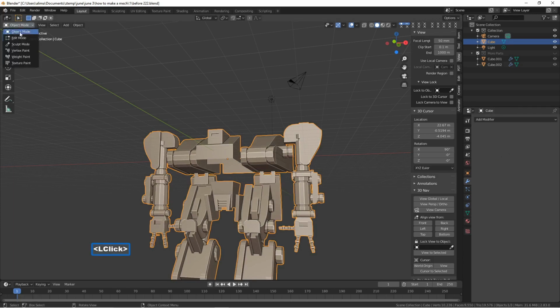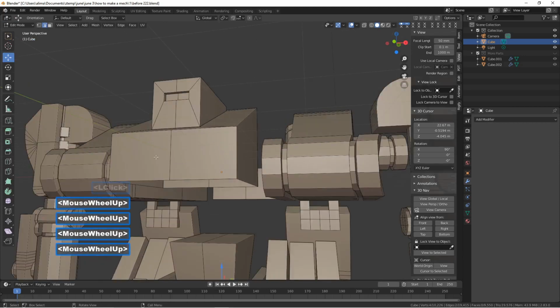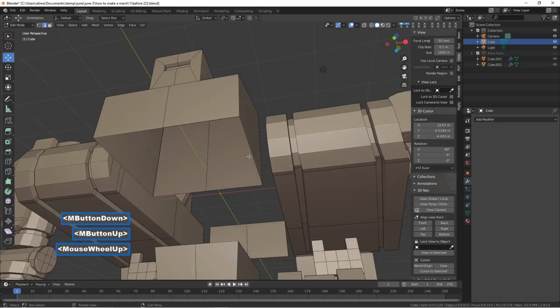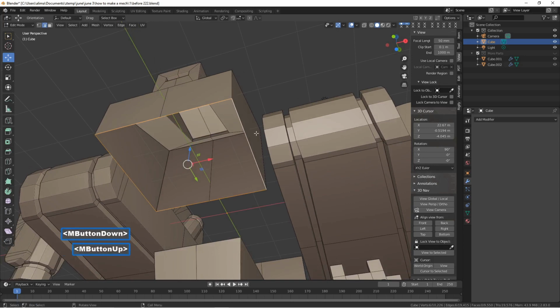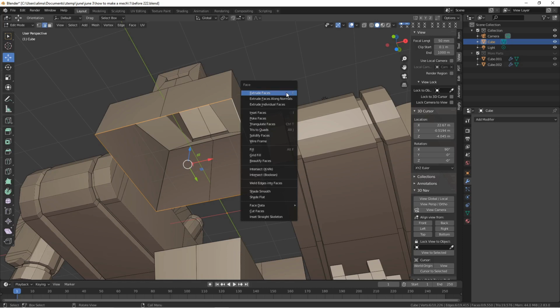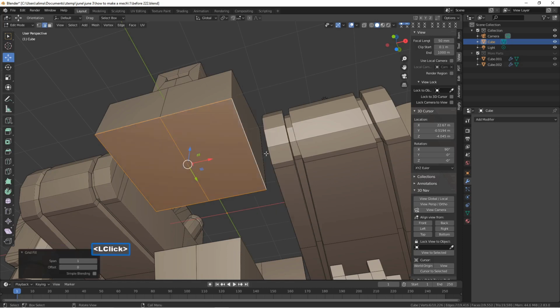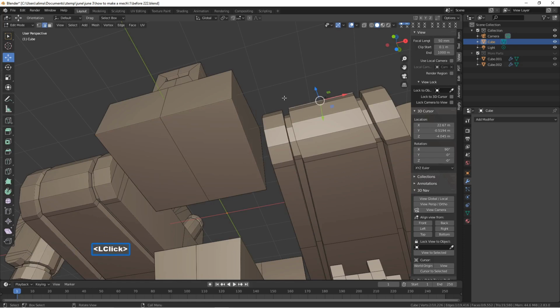I'm going to go back to the upper left. So one of the reasons why I did that is we're pretty much done with most of the work in here. Applying that makes this work here easier to do. So what we're going to do is hold Control, press F. When I say applying that, I meant the mirror modifier. We'll select Grid Fill. I'll left click to deselect.